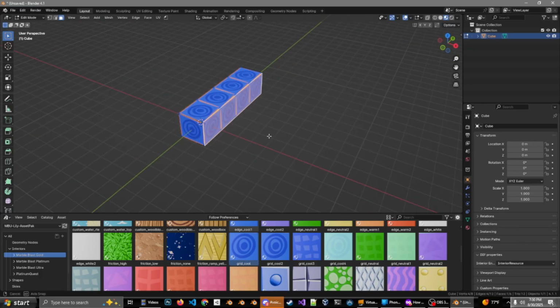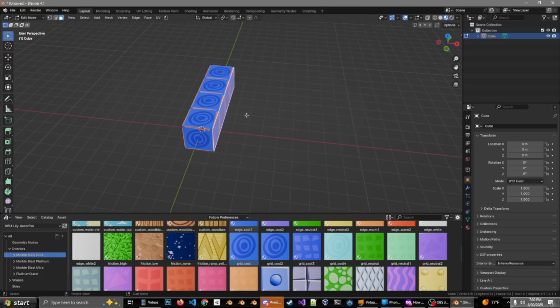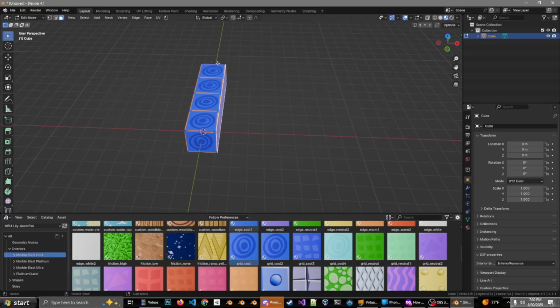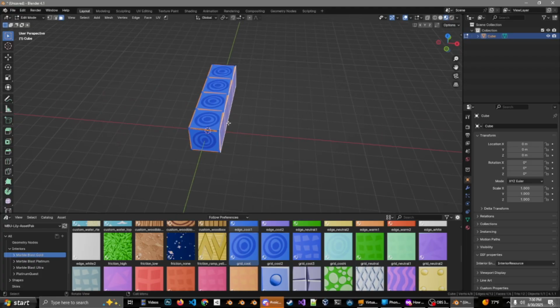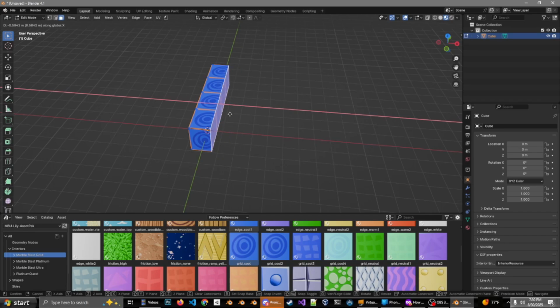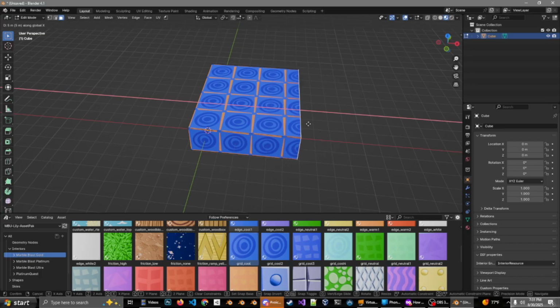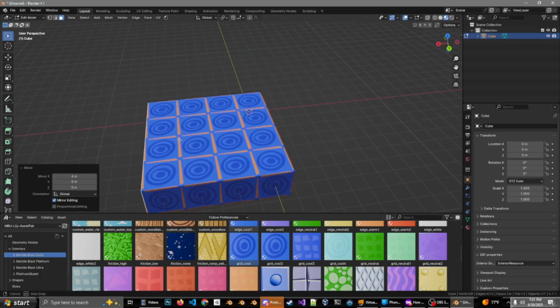And yeah, so let's just do a 4x4 platform since we already have 4 grids here. And let's hit G. And let's go ahead and lock it to the x-axis by hitting X. And if we hold Control, we can do it by the grid, so it looks perfect.